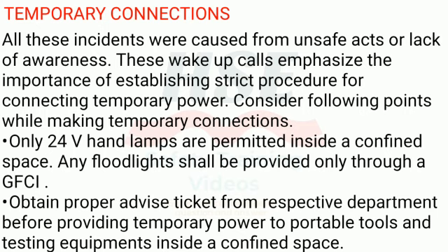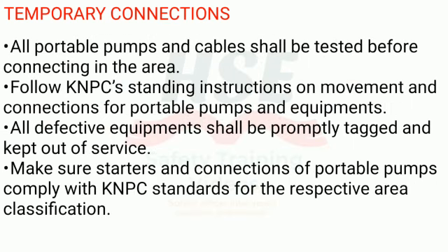Only 24V hand lamps are permitted inside a confined space. Any floodlights shall be provided only through a GFCI. Obtain proper advice ticket from respective department before providing temporary power to portable tools and testing equipments inside a confined space. All portable pumps and cables shall be tested before connecting in the area.